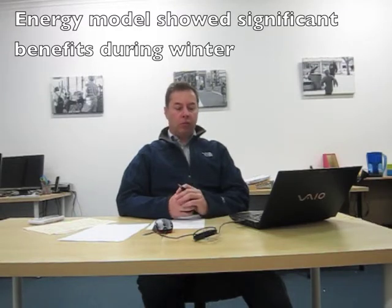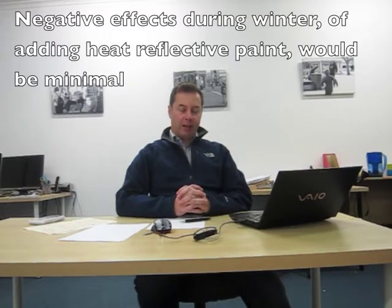The insulation would slightly increase this, so you'd have an 11.2 degrees indoor temperature compared to 9.6, which is 1.6 degrees higher. In addition, for wintertime performance, we also looked at the effect of adding heat-reflective paint onto the roof and what effect this would have on the internal temperature during wintertime. We found that there's no significant loss of temperature during wintertime.